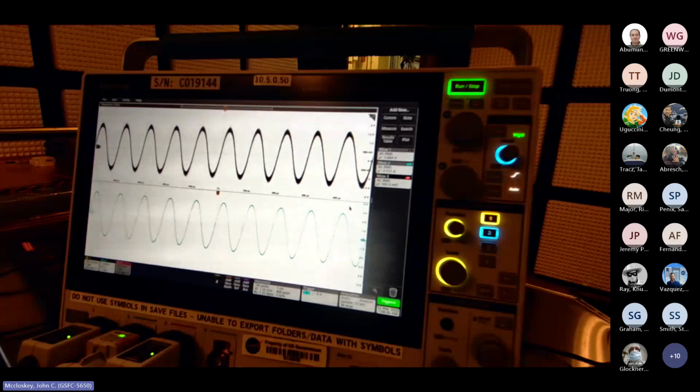And get on a couple temps. It was about minus 16.2 before. There we go, minus 16.2 dBm is what gives us basically 1.0, I'll call it 1.002. And the current is still right around, I'm sorry, 1.989 amps RMS. Okay.